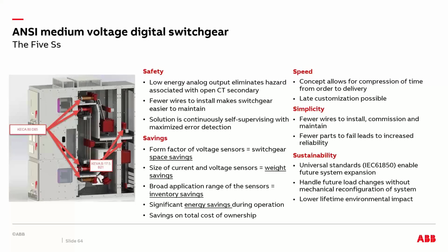Let me go into the benefits of having a medium voltage digital switchgear, the 5 S's, which are most important: safety, saving, speed, simplicity, and sustainability. So of course, safety comes first. This particular application eliminates the hazard of having an open CT secondary, and we have no CT saturation, so that is great. And then the solution is continuously self-supervising with maximized error detection.